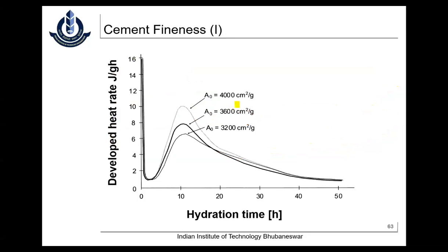Yes, and of course nowadays this is another basic problem which has been seen in the last couple of years. This is the grinding and the fineness. I noticed this in most of the blended cements. I have seen that some manufacturers, without naming them, whenever you're having 30-35% of fly ash, the quality should be good and reasonable, so that you will not have all these problems of grinding the cement.